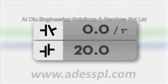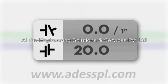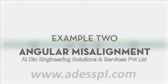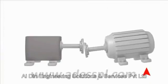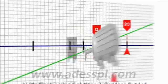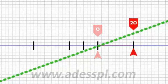The movable shaft center line is now offset from the stationary shaft center line by 20 thou at every point along its length. Because we've added the same amount to both front and back feet, the shafts are parallel. There is no angular misalignment, so our offset misalignment is 20 and our angularity is 0.